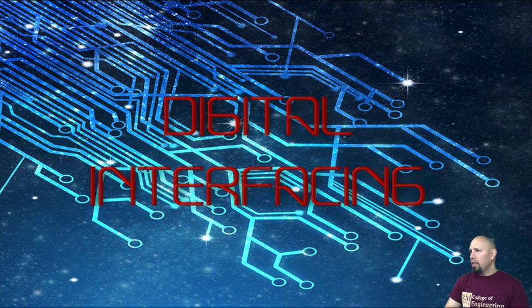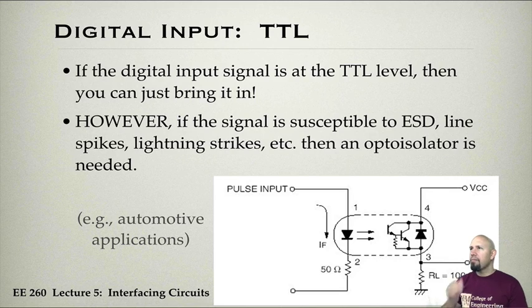Let's move on to the digital interfacing. First of all, we have TTL interfacing. Again, we may be in an environment that is very noisy. Theoretically, we have a digital signal at TTL level. However, the real world is still basically analog, which means even though we think that's 5 volts, it may be fluctuating, and it may fluctuate to the extent that it would fry our Arduino. In other words, you can get voltage spikes that would cause the Arduino to fry. Not a good situation.